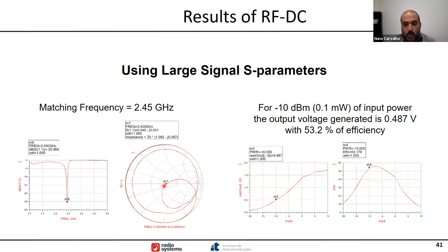So you can tell me, if I change power, you need another impedance. If I change down or you change up, probably the input matching network should change. So what we normally do is select the number of powers at which we want our device to work. You measure scattering parameters at all of them, and we normally do an average, because at this moment we cannot tune the input matching network.